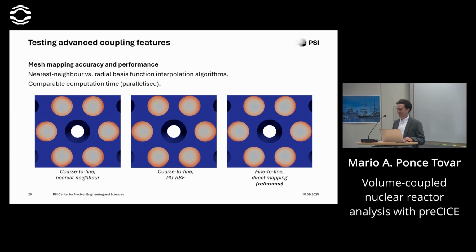And I was wondering, for the performance runs that you did, could you comment what were the largest meshes and the largest MPI ranks that you used for the volume-volume coupling? Sure. It was not too many ranks. It was, I think, 24 CPUs for these cases, and they were dividing up these meshes that were like 5 to 10 million cells, roughly.